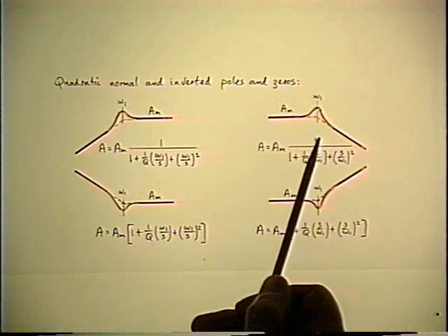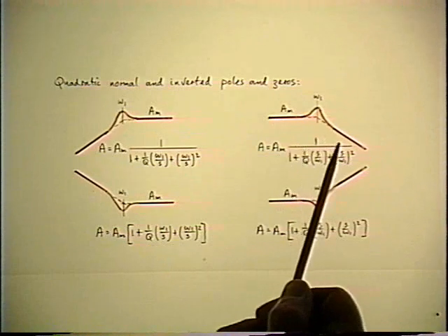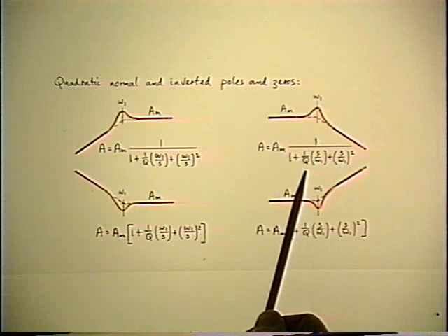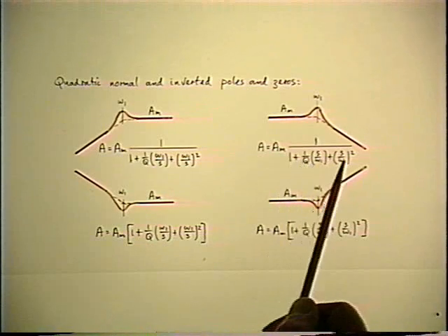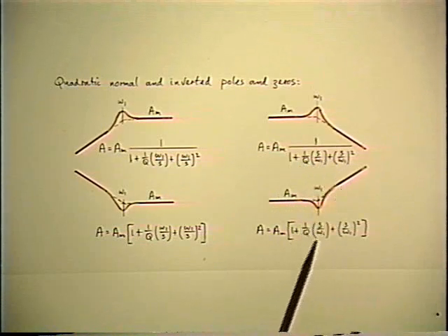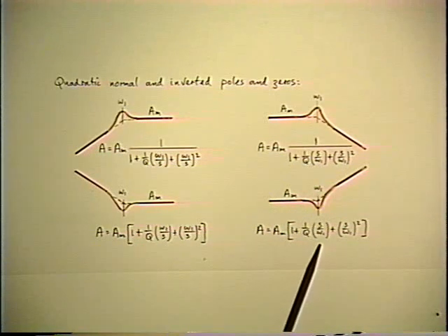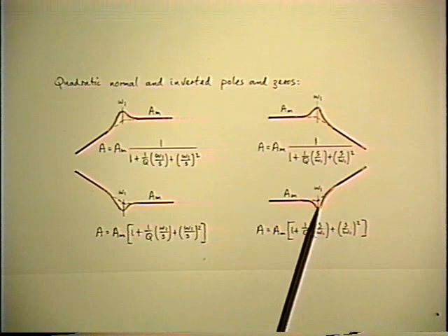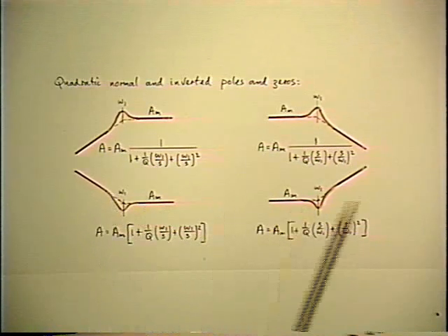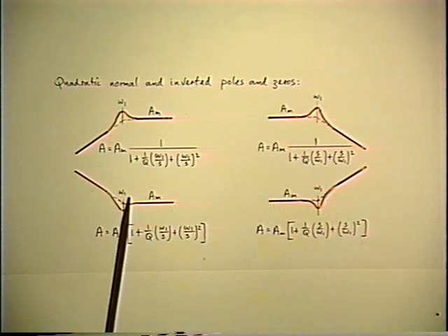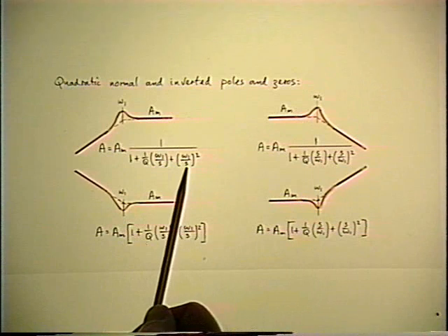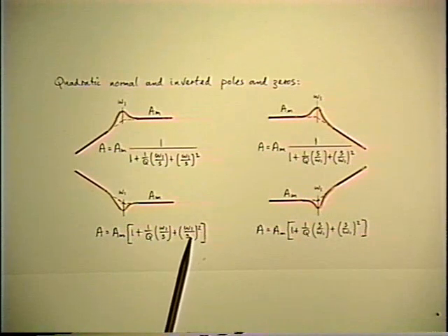On the right-hand side, there's the usual double pole low-pass filter, represented by a quadratic in frequency with a certain Q factor. And again, moving the entire quadratic from the denominator to the numerator gives you a quadratic pair of zeros, corresponding to a vertical inversion of the asymptote diagram. But the same thing works if you reverse the frequency direction. Now the diagram reverses, and that is equivalent to inverting the s terms.